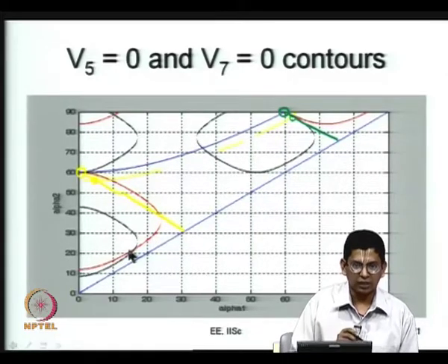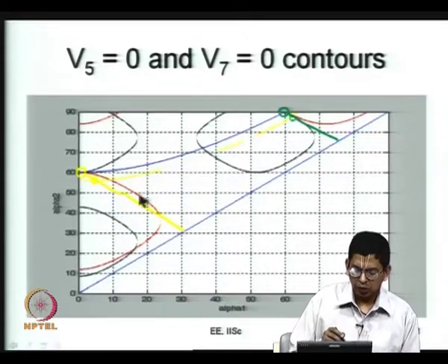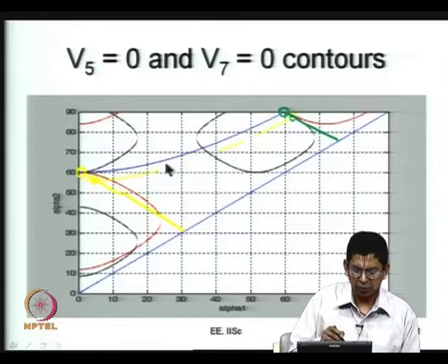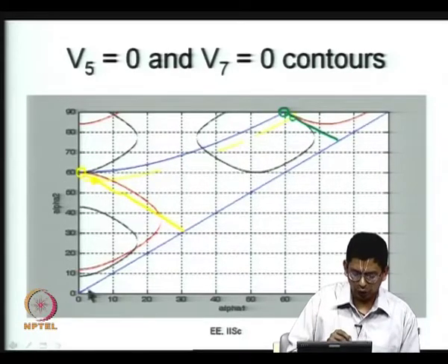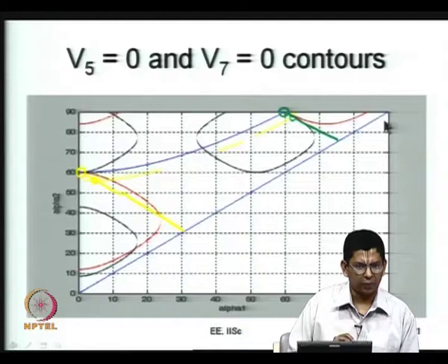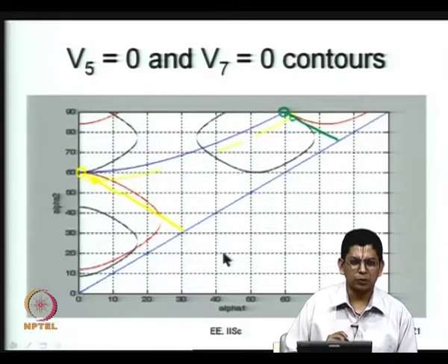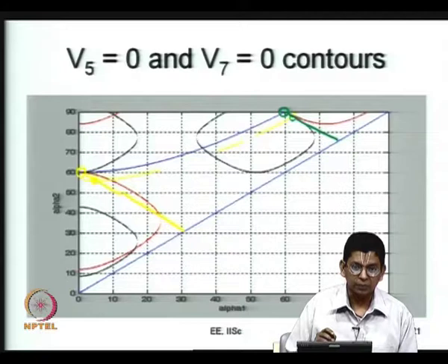So, you can look for any curve that goes through that or goes close to this and things like this now. So, several possible contours you can draw, infinite number of contours. You can start from any point on V1 equal to 0 and you can choose any point on V1 equal to 1, and from that point to this point there are several contours, again infinite number of contours. It basically tells you that infinite number of PWM techniques are possible, but not all PWM techniques are equally good, right. How do you choose those good techniques now?